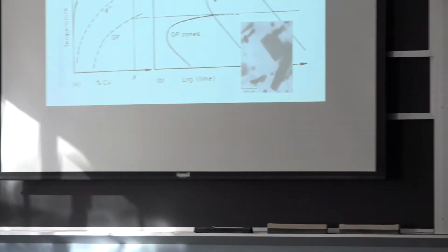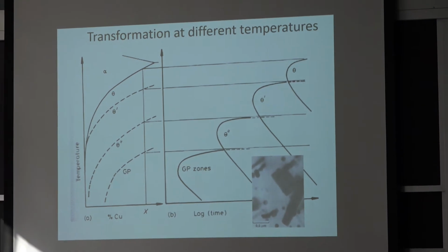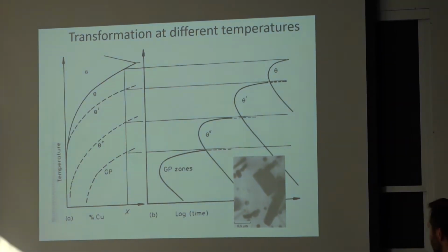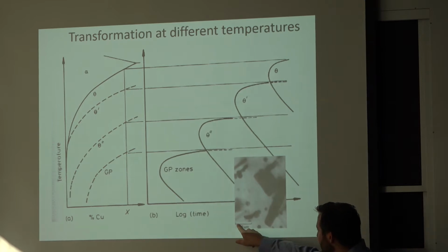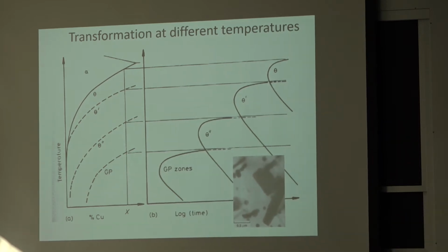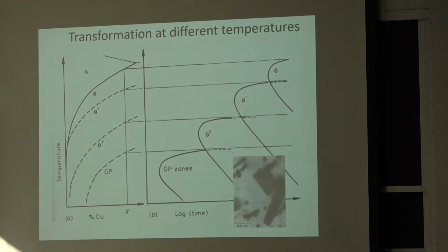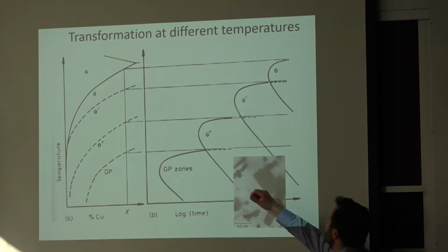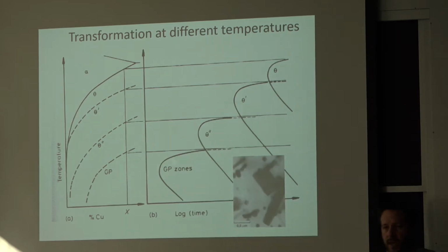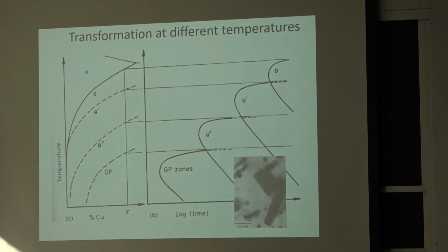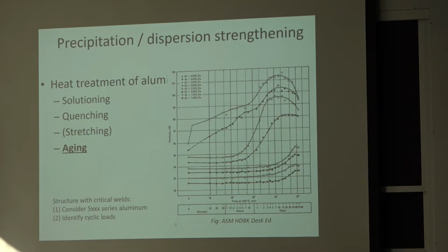We talked last time about how you take aluminum and make it stronger by forming these precipitates. I won't go back to all that we discussed, but maybe I'll point out this scale here is 0.5 micrometer for these precipitates. It was done using a transmission electron microscope. That's how you find out what you have. And we talked about the precipitates being much smaller at the low temperature. One thing I may not have emphasized enough is these intermediate precipitates that give you the highest strength, because they are obstacles that are still part of the grains, so they impede the movement of dislocations. And they're bigger than these very, very small ones that are there on the screen.